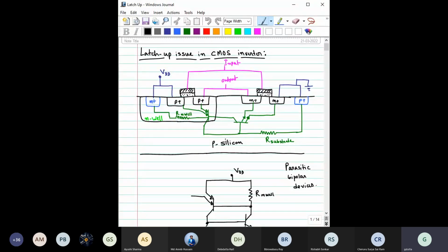This is P silicon, this is N plus, this is N plus, this is oxide, this is gate. So this is PMOS, right? Because here, when you apply negative voltage with respect to source, then what will happen? Here the charges will be induced, that is, holes would be induced here.